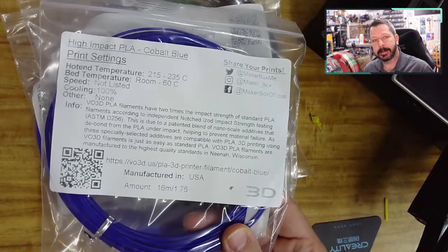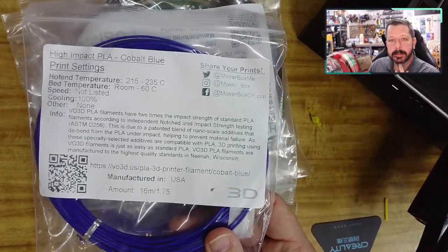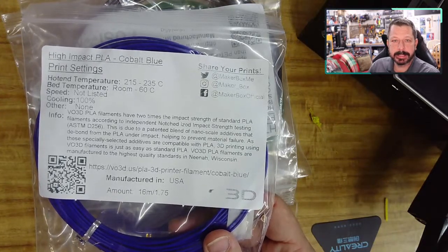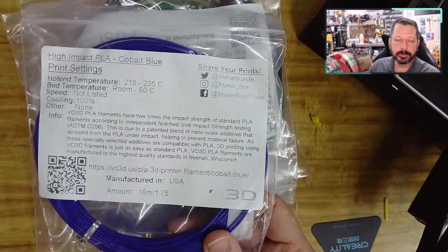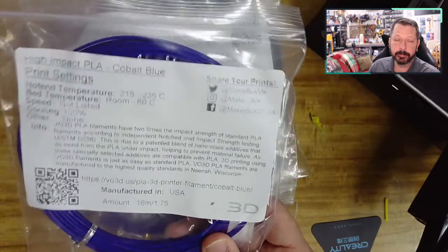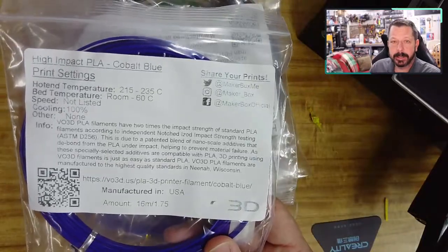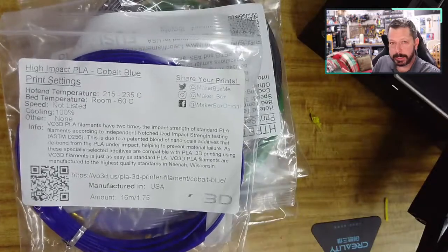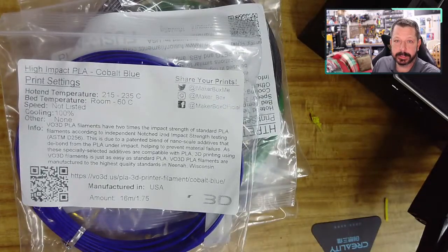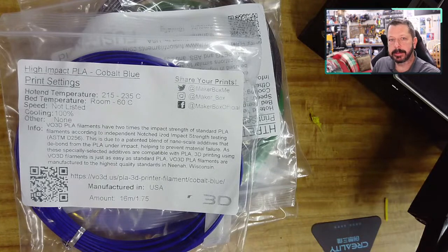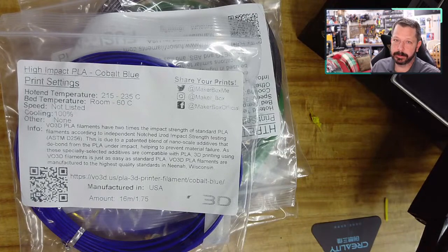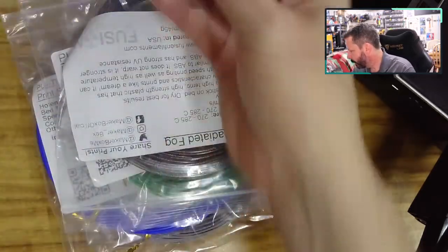There are tests being done, but none have really indicated that the particles released while you're printing, even from regular filament, not even stuff with nanoparticles in it, are a problem until you get into an enclosed space with a lot of printers printing continuously. So in an open space with a printer printing, it doesn't seem to be a health issue until you get into tight spaces with lots of printers going constantly. All right.